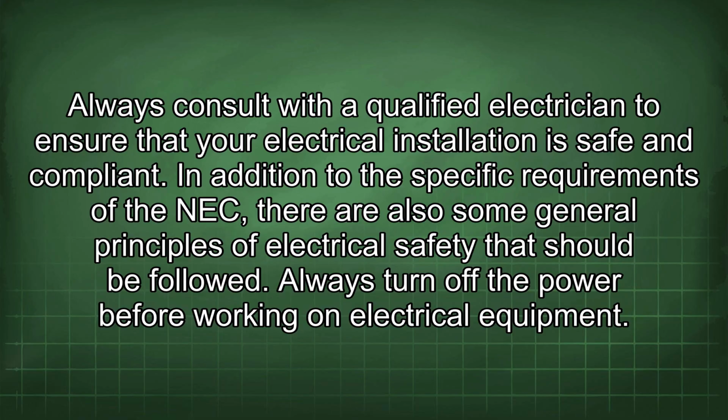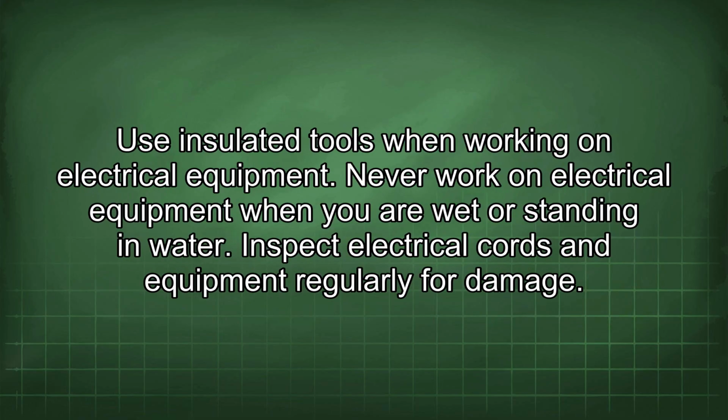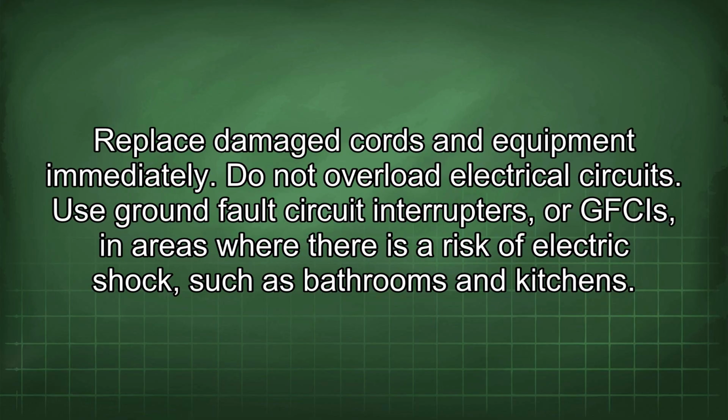In addition to the specific requirements of the NEC, there are also some general principles of electrical safety that should be followed. Always turn off the power before working on electrical equipment. Use insulated tools when working on electrical equipment. Never work on electrical equipment when you are wet or standing in water. Inspect electrical cords and equipment regularly for damage. Replace damaged cords and equipment immediately. Do not overload electrical circuits.